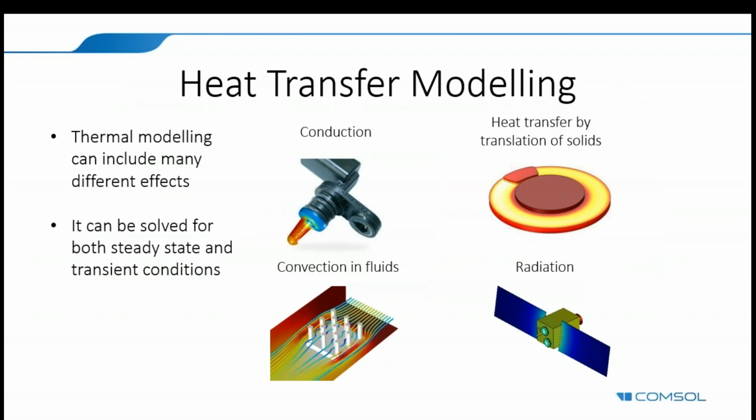So that takes me on now to the heat transfer modeling. I guess this is the last branch of physics that I wanted to discuss. So COMSOL supports heat transfer modeling by the three main mechanisms of heat transfer. So you can look at heat transfer by conduction, convection, and radiation. Of course, thermal conduction is where you're looking at the transfer of energy within a rigidly bonded material from an area of high temperature to low temperature. And the rate of conducted heat, or the flux, is proportional to the temperature gradient and the thermal conductivity of the material.